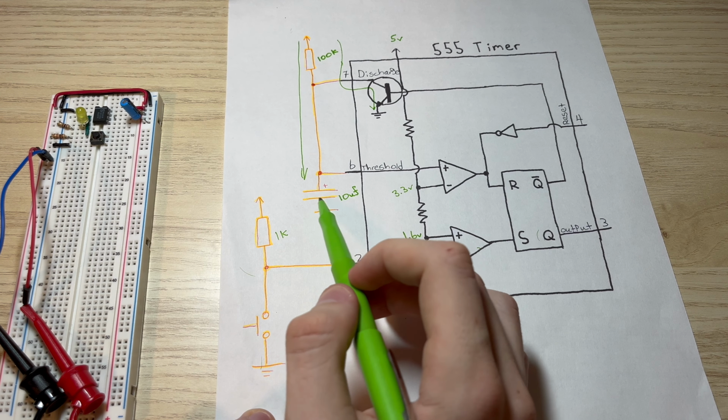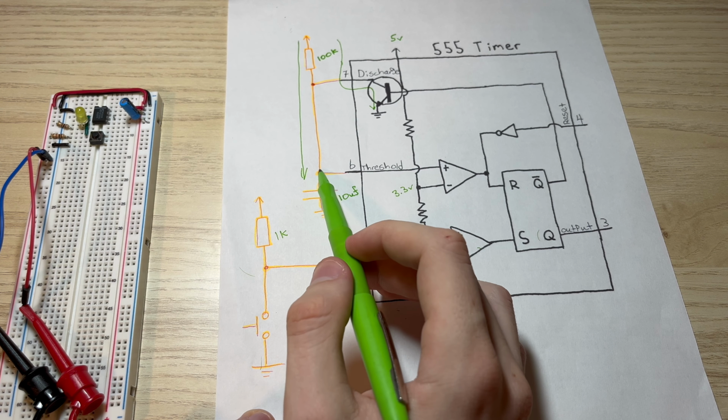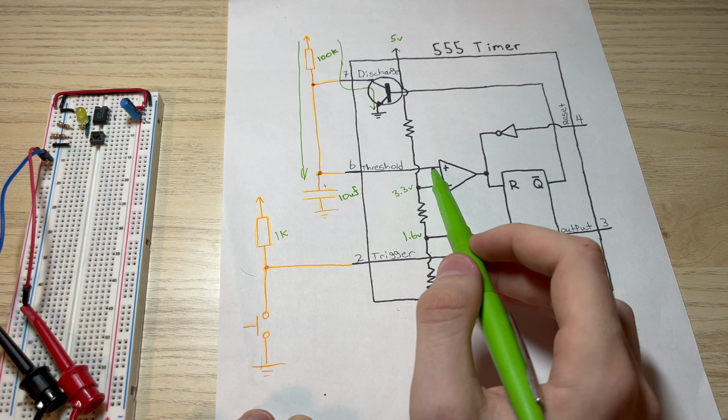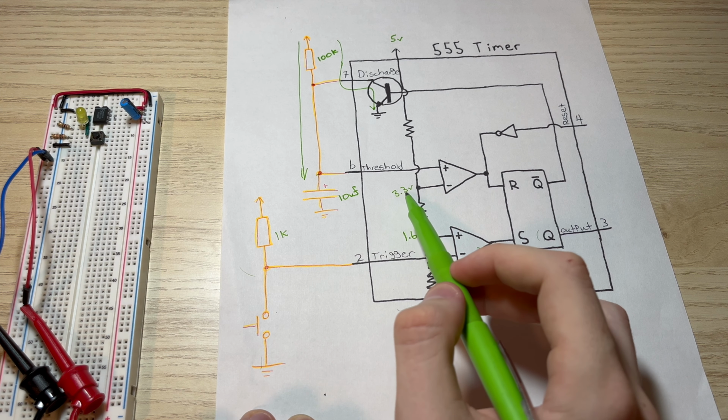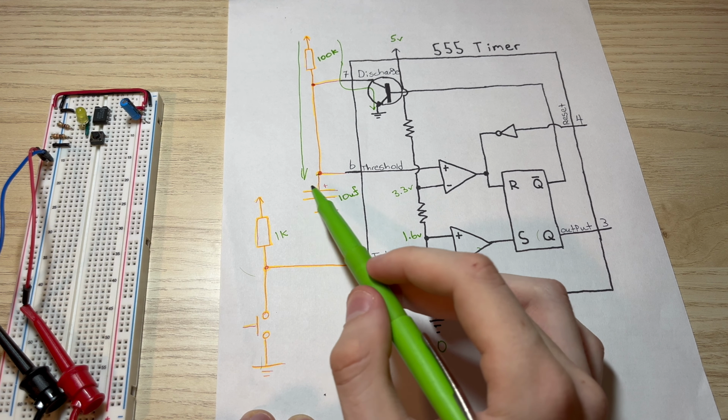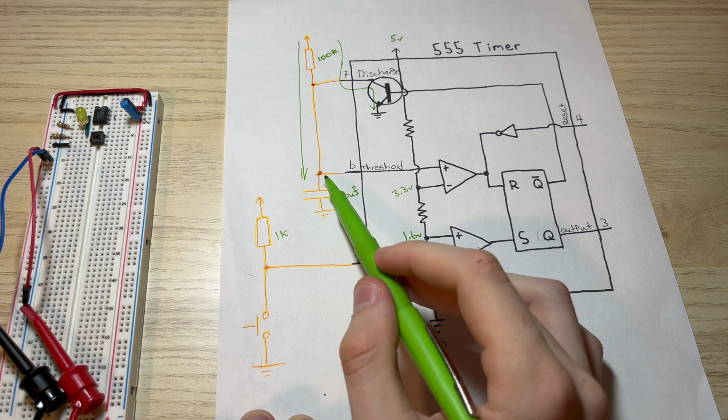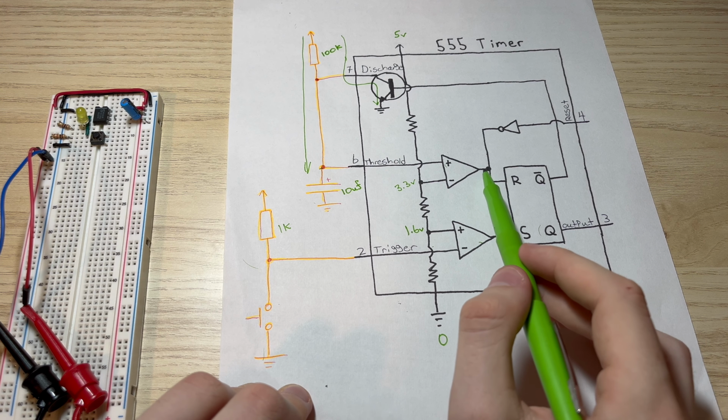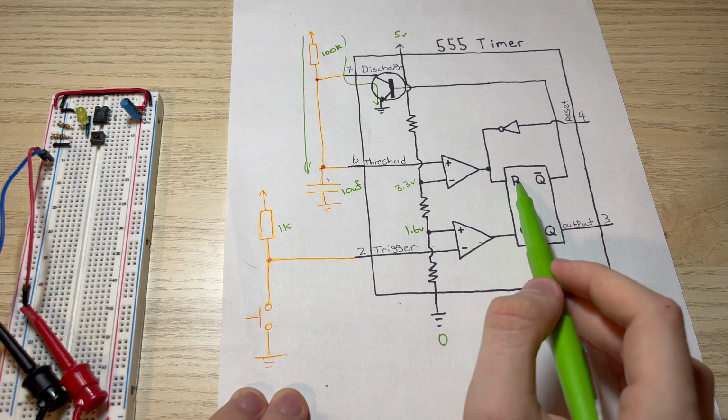Now this capacitor is charging up, and eventually it will charge up to a certain voltage. As soon as it gets higher than 3.3 volts here, as the capacitor charges up slowly, suddenly it'll reset. We can see how this resistor and capacitor control when this LED turns off, because that capacitor was charging up, and as soon as it passed 3.3 volts, it had a positive output, meaning it would reset the latch.